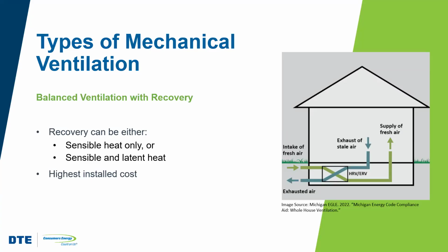And this device that does this exchange is what we call a recovery ventilator. That recovery can either be sensible heat only, so it can just be temperature change, or it can include moisture, right? So it could be sensible and latent heat. When it includes both sensible and latent heat, we call it energy recovery.